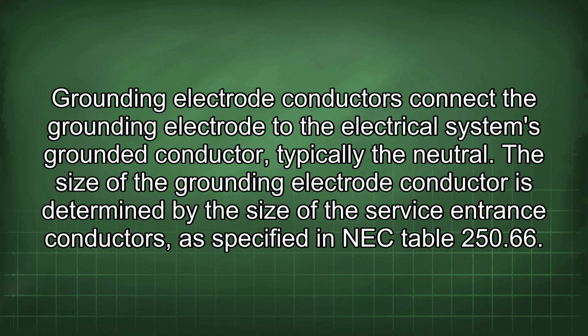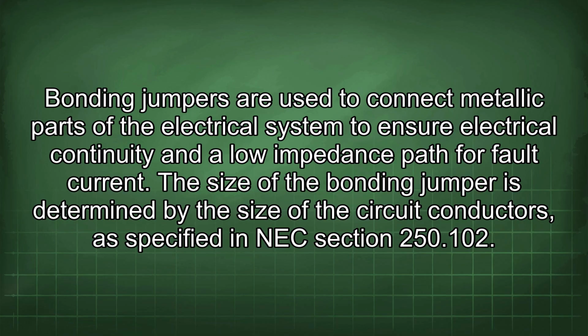Grounding electrode conductors connect the grounding electrode to the electrical system's grounded conductor, typically the neutral. The size of the grounding electrode conductor is determined by the size of the service entrance conductors, as specified in NEC Table 250.66.